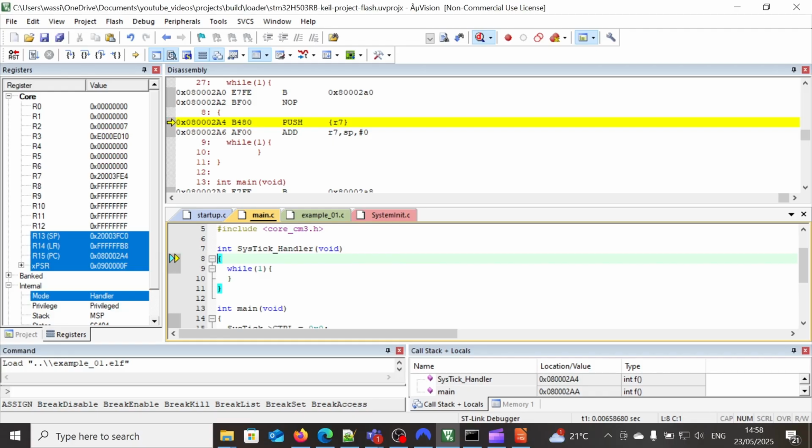The SysTick Timer can be used, for instance, to measure the time for some software API calls. It can be used as well to preempt some thread or process, and this is quite suitable for a real-time operating system that is deployed in our microcontroller.